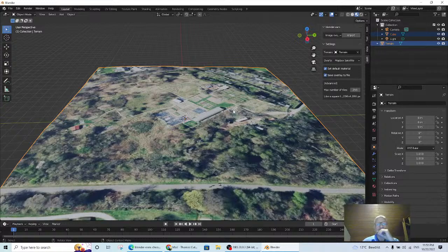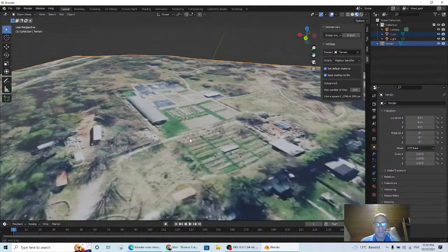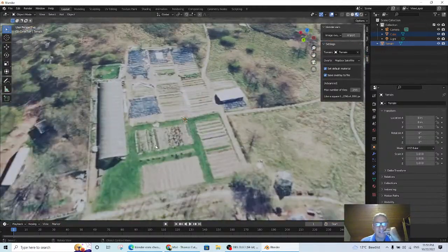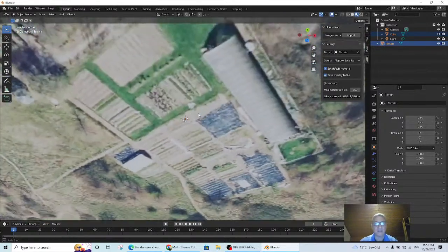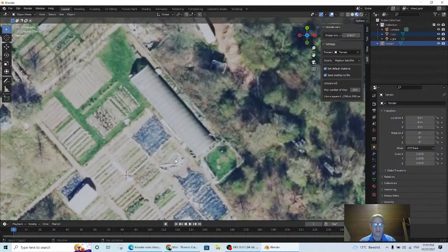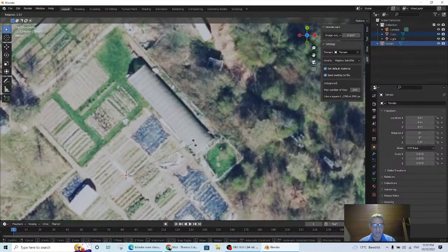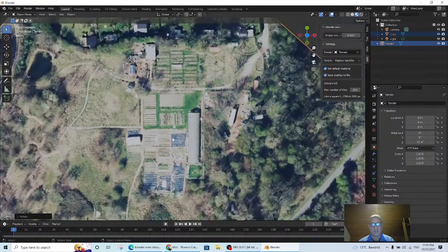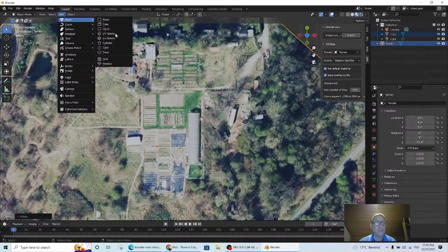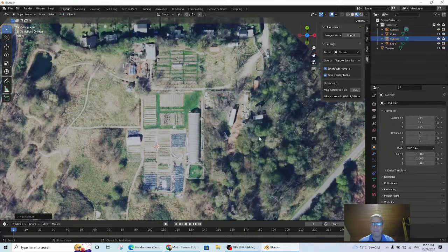All right. So I'm going to use this as my base when I go into Unity and then start building things from there. But I'll also have it as a reference in Blender. So if I want to try to do some mesh modeling, for example, I can take this greenhouse and hit the 7 key and then shift and move over, and let me also rotate this to make it easier to draw. And now I can go in and add a mesh and add a cylinder.